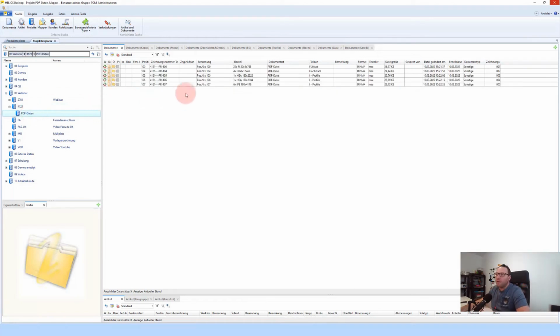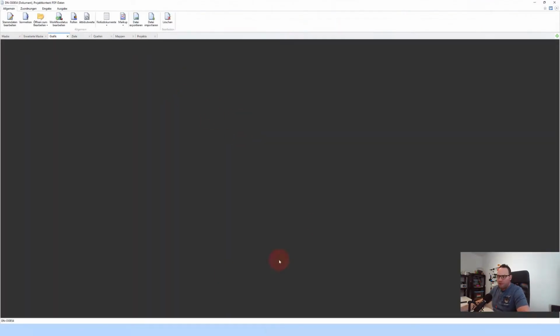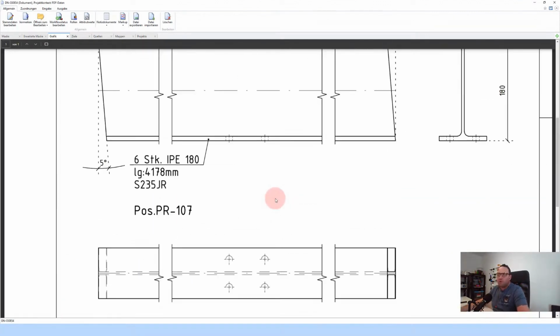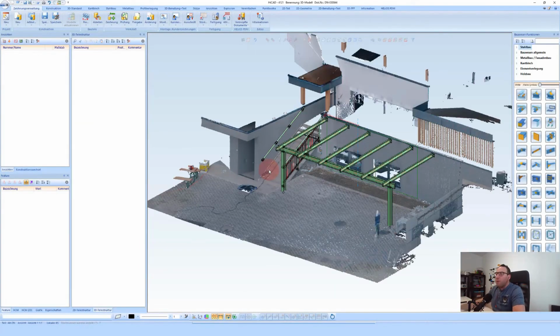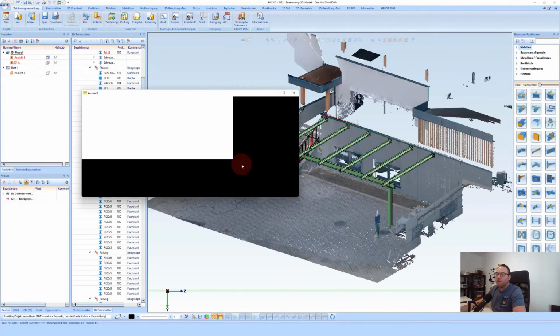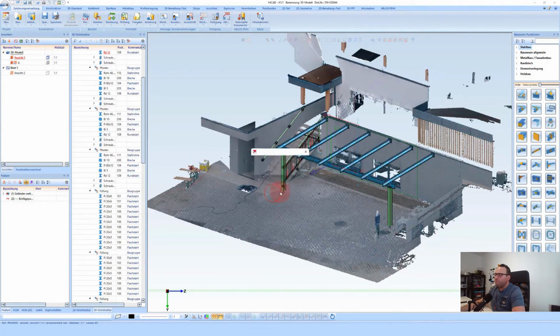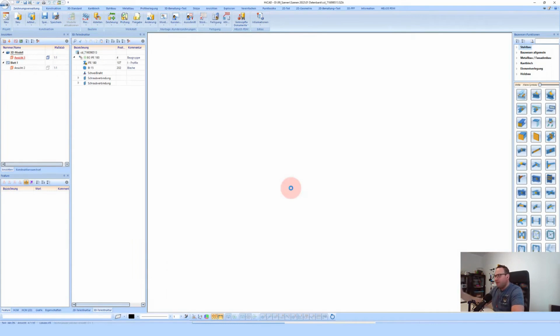For this, the HiCAD with HELiOS in combination has already generated a PDF for me. That means I also always have an automated PDF in the background here, which I can easily view, print, share, or whatever. And it is important that, for example, when I also create assembly drawings here, meaning I want to generate an assembly drawing from this, or even two, then when the assembly drawing is generated according to my rule set, which I can adjust again, I can also say that if a position flag with the position number 100 is present, then I know where to find this part.